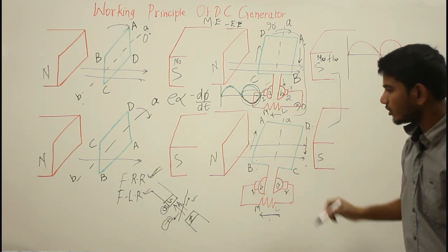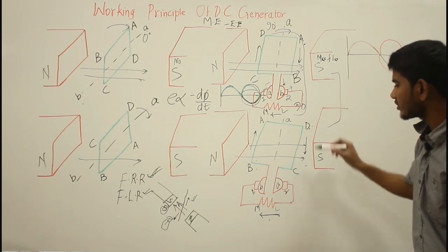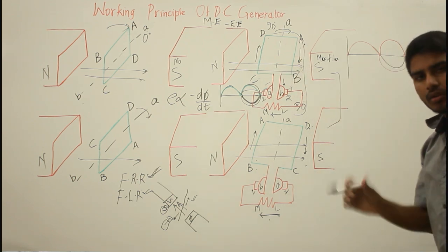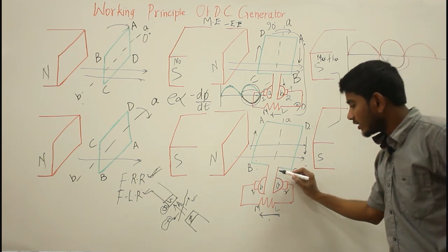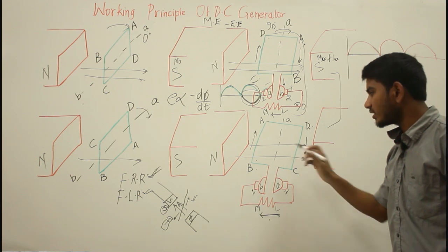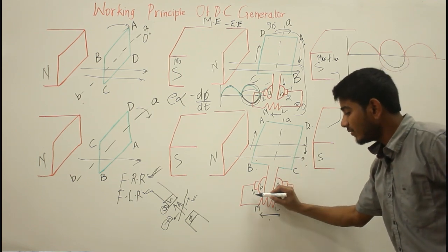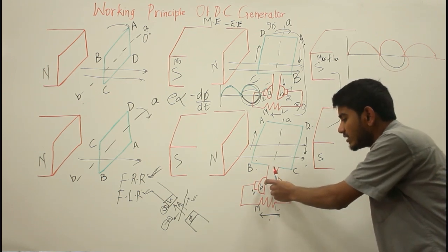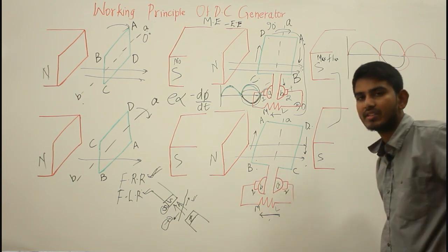as the current is going to reverse, because from B to A it is flowing, here from A to B, the current is reversed, here D to C, here C to D, the current is reversed. Now I know the current is reversed, then if I reverse the terminals of my armature coils or armature turn, then after reversing it, I can make it reverse by switching the commutator segments between the two brushes.